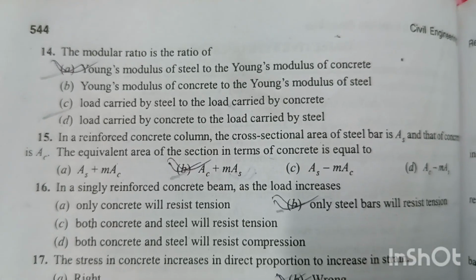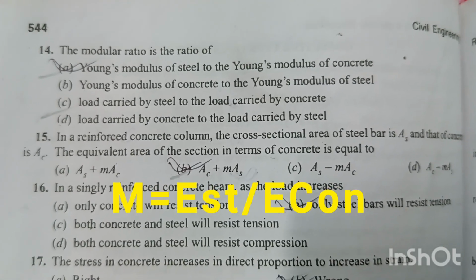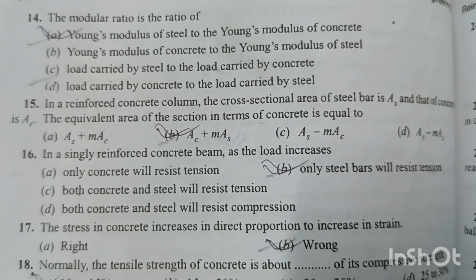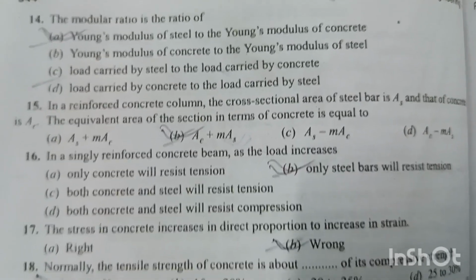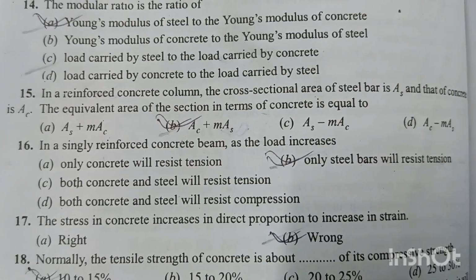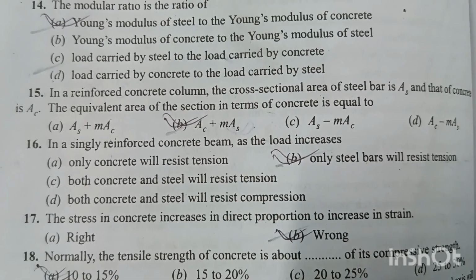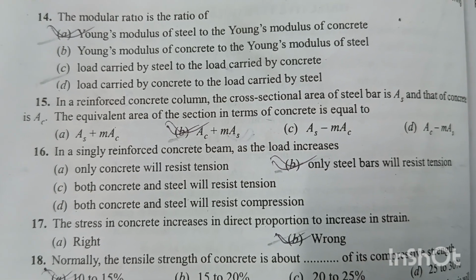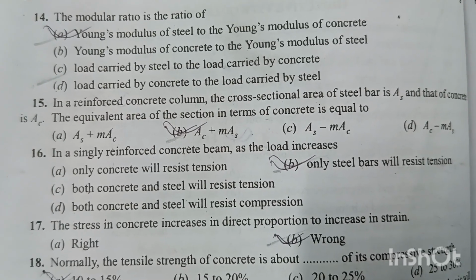Question number 14. The modular ratio is the ratio of Young's modulus of steel to the Young's modulus of concrete. Option A is the right answer. Question number 15. In a reinforced concrete column, the cross-sectional area of steel bar is AS and that of concrete is AC. The equivalent area of the section in terms of concrete is equal to AC plus m into AS, where m is the modular ratio. Option B is the right answer. If we multiply the steel area with the modular ratio, we get the equivalent concrete area of the reinforcement.